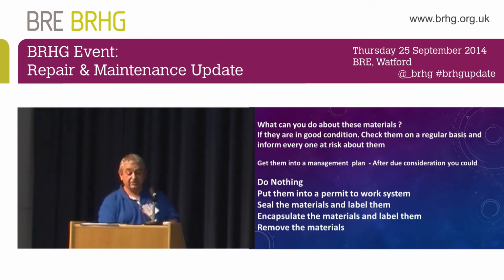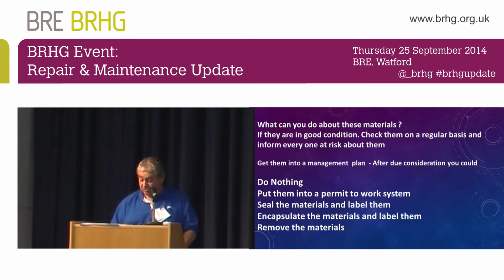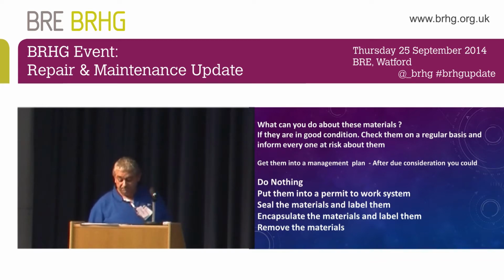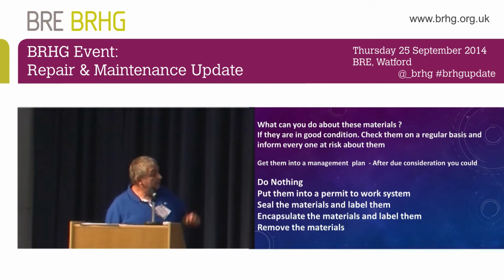If they're in good condition, check them on a regular basis, inform everyone at risk about them, get them into a management plan, and after due consideration, you could do nothing. If there's no risk, do nothing, leave it alone. Might be worth painting it, sealing it, putting a sticker on it. Put them into a permit to work system. No one goes near this unless you've got a permit to work, so that they know what they're working near, know what the risks are.